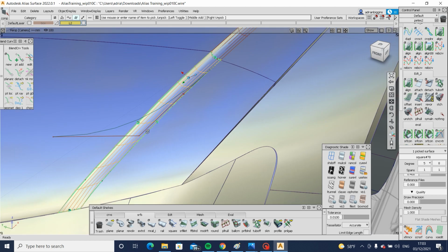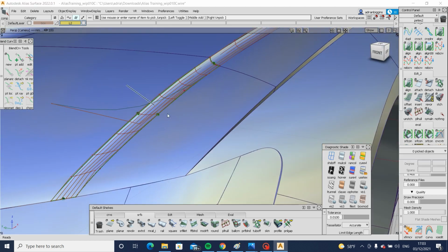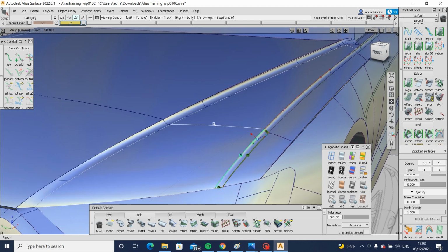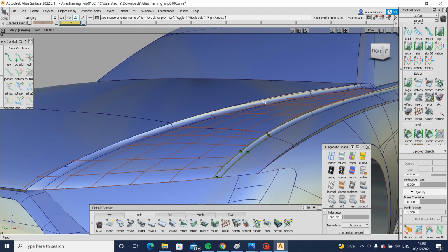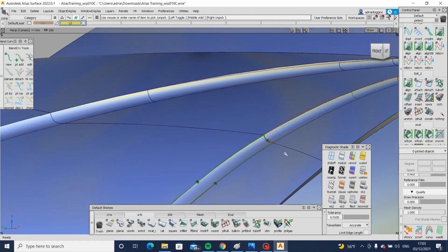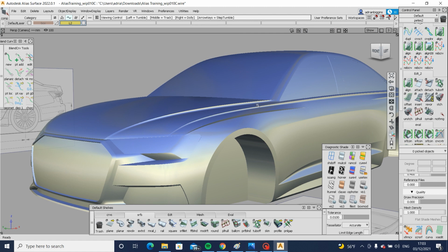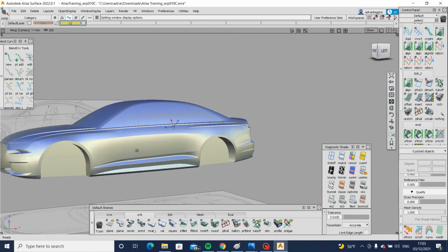So I allow multiple rows of CVs when it comes to fillets. I feel like it's not that important. It is important when you're using big slabs that you keep it to 5x5 maximum, because you're trying to align curvature and control things easily. But when it's just fillets and rads, it's not a massive deal. They're just there to finish things off. They're not there as a primary design surface.